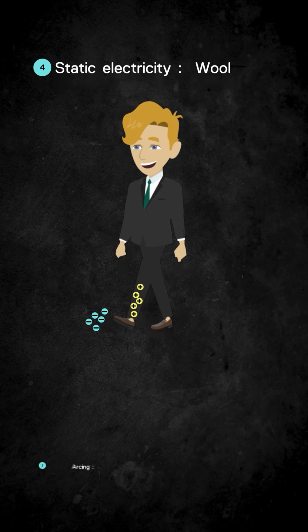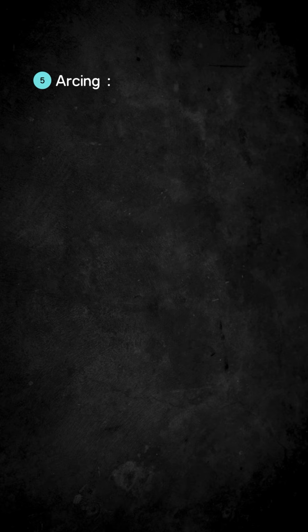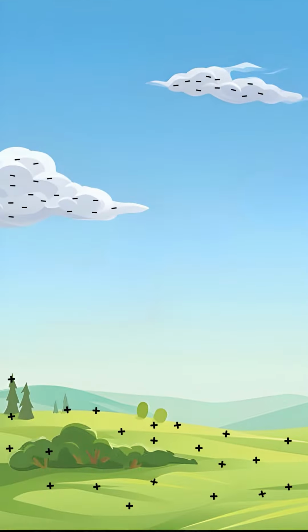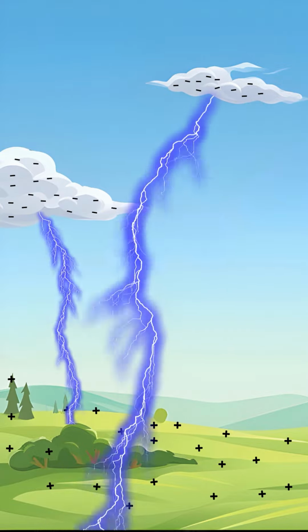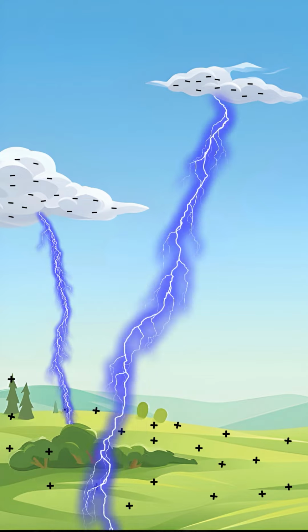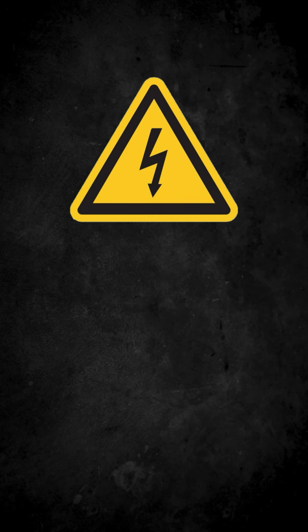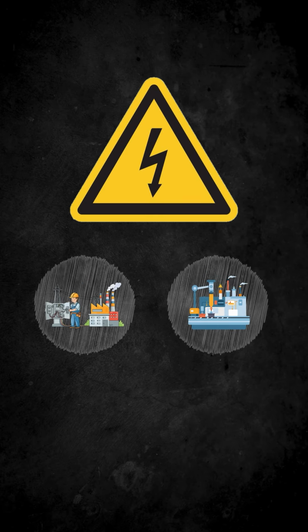One final additional point, how lightning occurs, which we'll talk about later when we discuss conductors. When a very high voltage difference forms between the clouds and the ground, even air, which is non-conductive, turns into a conductor. So the lightning process occurs, which is an instantaneous discharge of the charge. This point is very important when dealing with high voltage, especially inside factories or inside electricity companies, because a high rise in voltage difference between 2 points may turn air into a conductor.